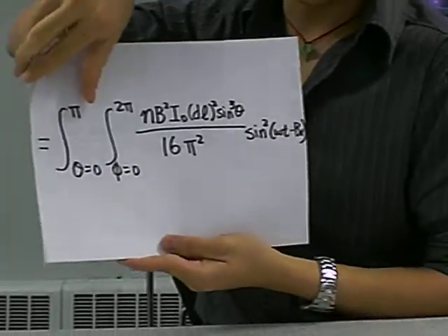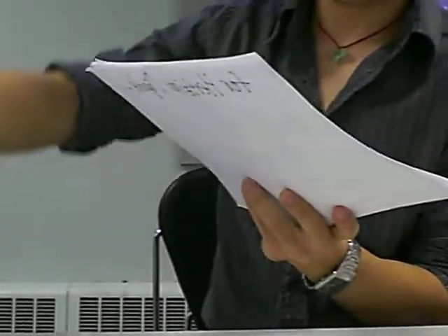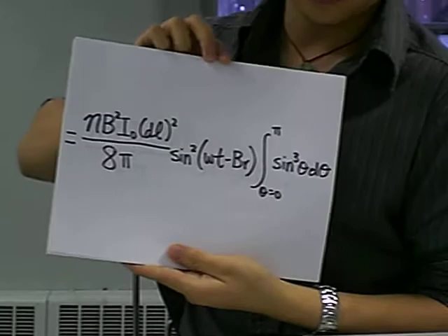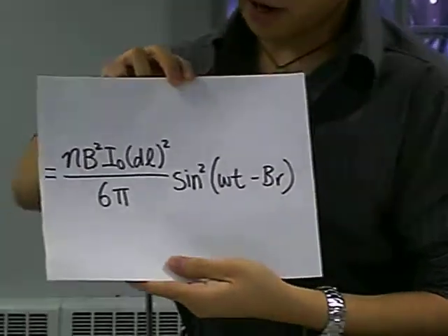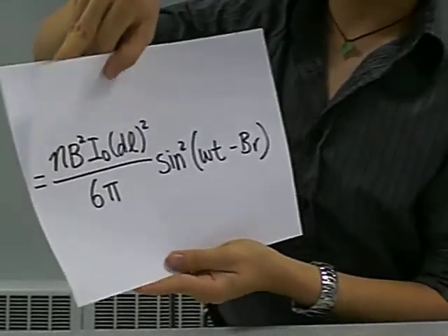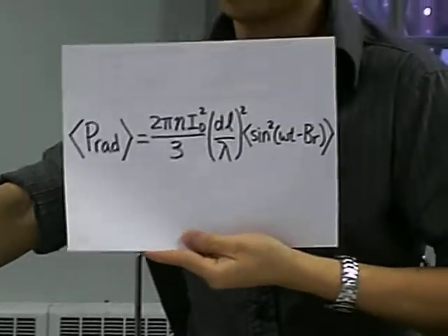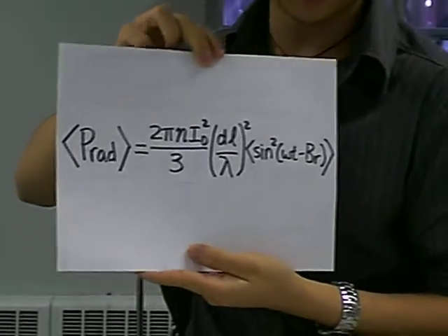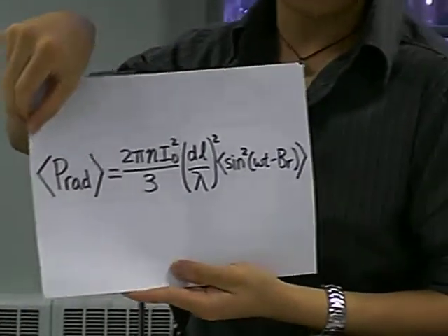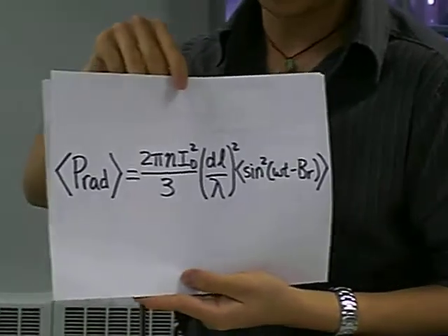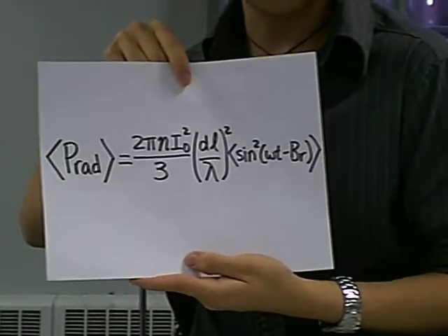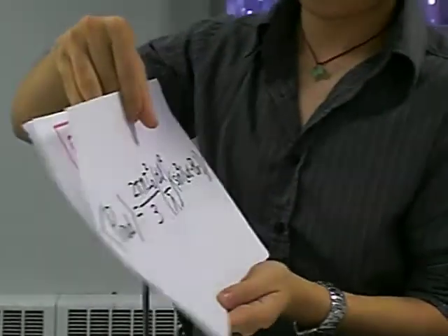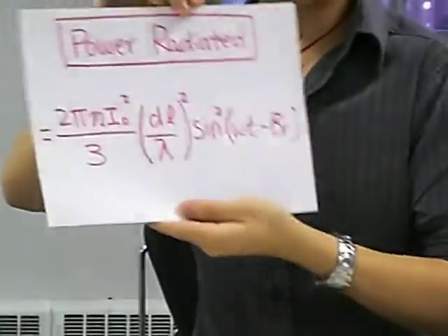This is after we plug it in. First we take our integral with respect to phi, then with respect to theta. Finally, we manipulate this expression a little algebraically to get this. So it is the same expression, just manipulated a little. Now this is our power radiated out of a Hertzian dipole, at a distance r from the dipole that is again large enough that it is much greater than 1 over beta. So this is our total power radiated.